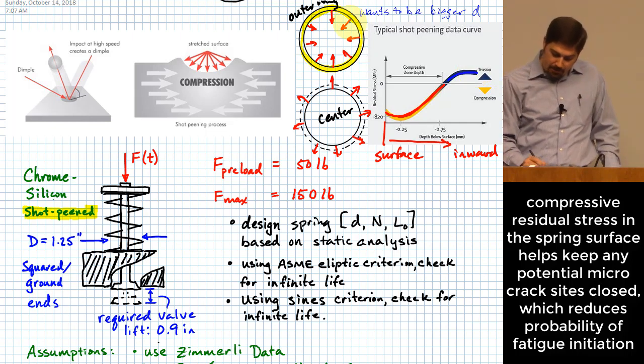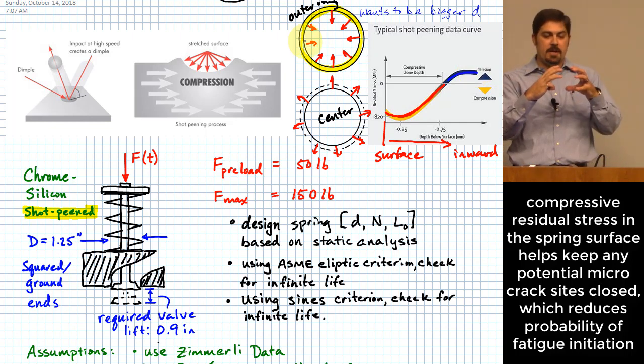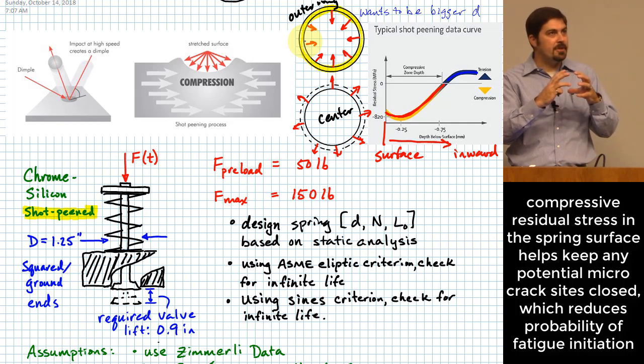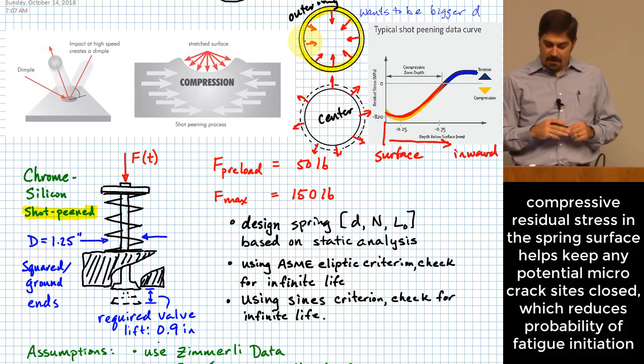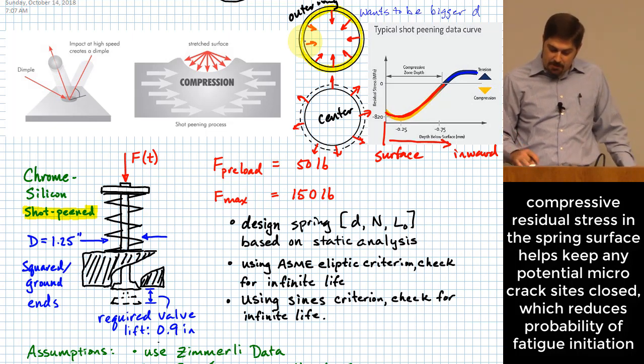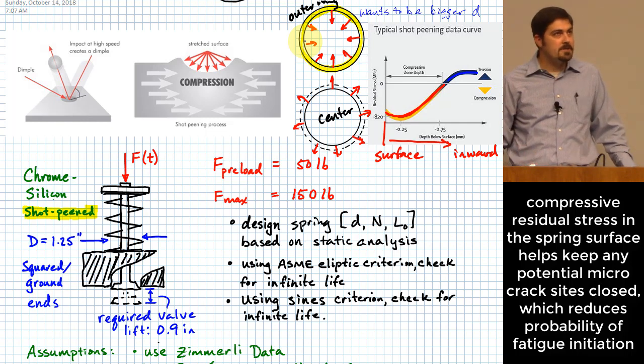And so what happens by building up this compressive stress tends to close cracks, right? So even as we stress this material in a repeated fashion, the fact that we've built up this compressive stress in the surface of the material tends to close those cracks, and it tends to make it less susceptible to this phenomenon of fatigue. Okay, so that's, like I said, the primary place where this is seen is in the building of springs, but this is not an unknown process to building of other kinds of machine parts as well. You can build up compressive stress in the surface, and that can be helpful.